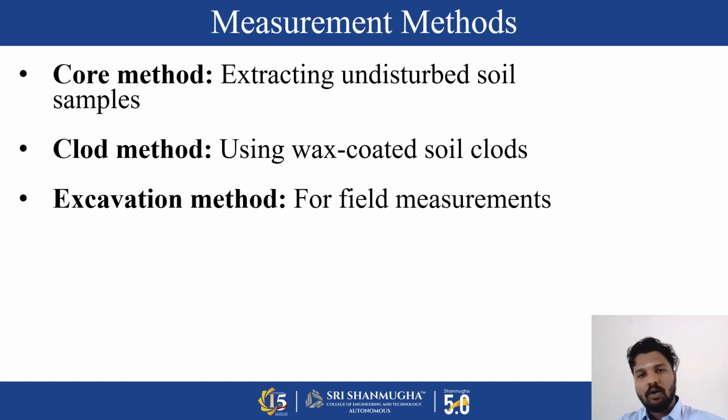In the core method, we extract undisturbed soil samples of known volume. This is commonly used to measure bulk density. The second one is the clod method, where we use wax coated soil clods to determine the volume by displacement. The third one is the excavation method, used for large scale or field measurements.